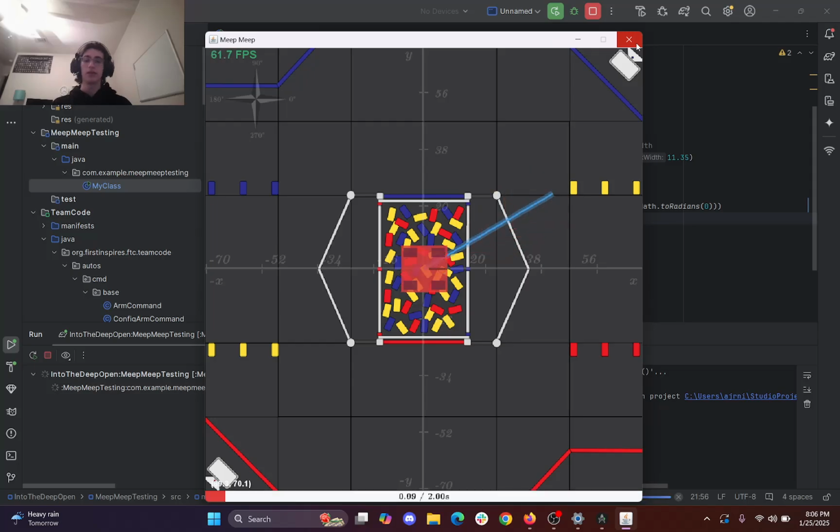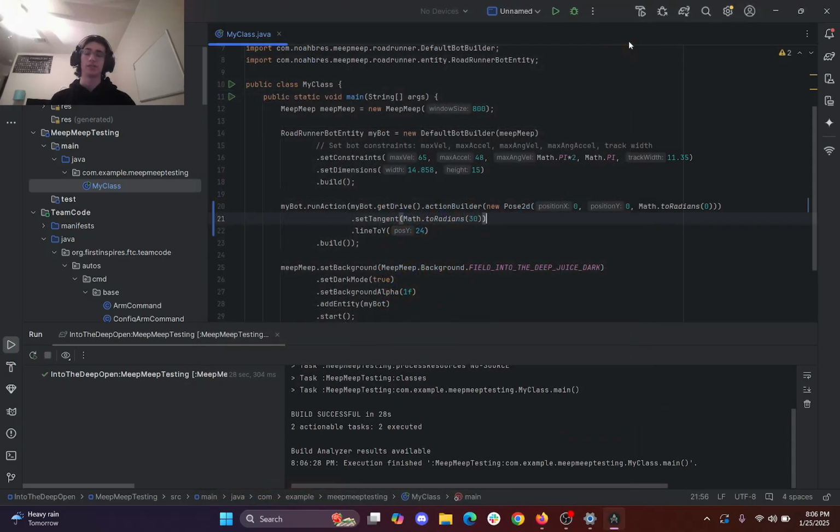Lines are pretty simple. I wouldn't recommend using them purely because you can't, by default, enter a specific set of coordinates you want to reach. You can calculate the angle you'd need to travel to reach a specific coordinate if you'd like to with some basic trig, but it's generally easier to use splines because you can specify the start and end points. So I would highly recommend using splines instead if you can.